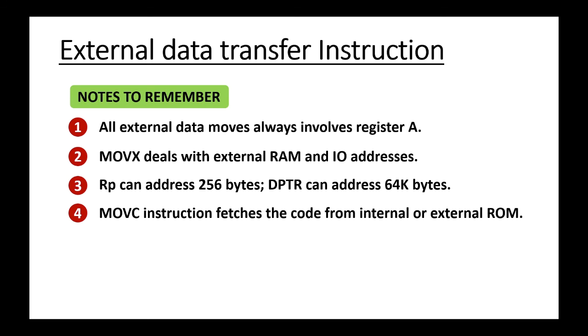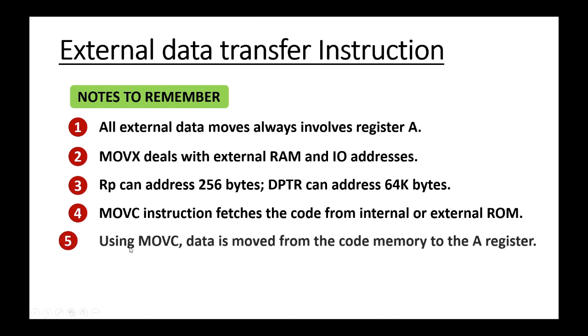So if you want to know the details of MOVC, you can watch the previous video in which the MOVC instruction is properly explained. Using MOVC, data is moved from the code memory, which is the ROM, to the accumulator. So the accumulator is always involved when there is an external movement. So this is all about the data transfer instructions.